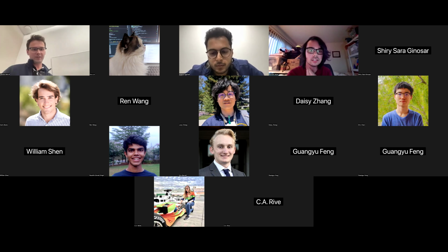Yeah, so that exact task we're doing teleop. One of the problems with that exact task is the robot hand cannot touch, so it cannot feel the grape. And also the human teleoperator cannot feel what the robot hand is feeling. There's no haptic feedback to the teleoperator itself, which makes that task quite tricky. So really the only way we're able to do that is because the robot hand is fairly soft and the compliance of the finger itself is not crushing the grape.